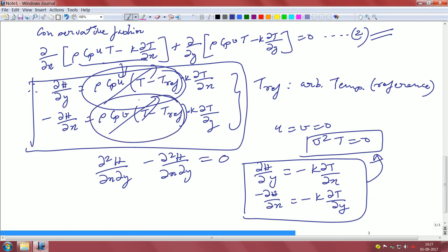Do you see these terms? These additional terms come into the picture, which basically represent deviation of the lines. So, it is no longer the same as your isotherm. The convective heat transfer mode represents all these deviations, these additional terms which come due to the velocity component only. So, this is a useful way if you want to visualize.